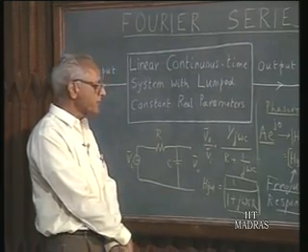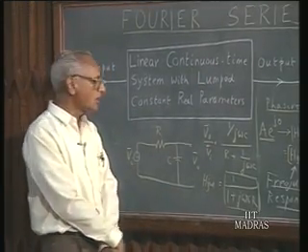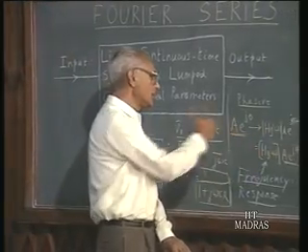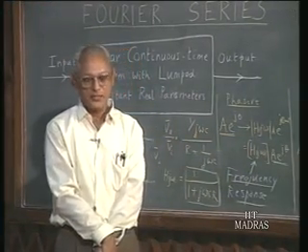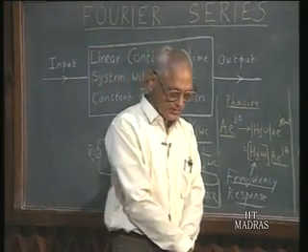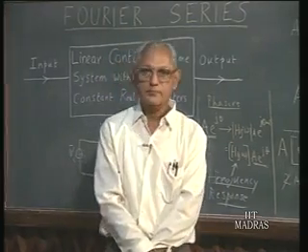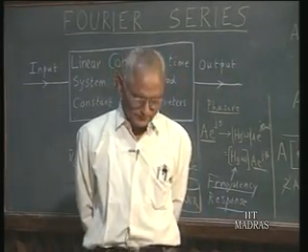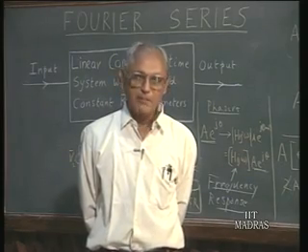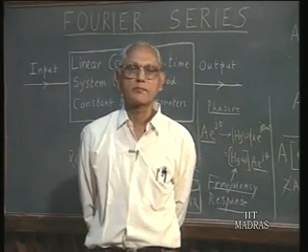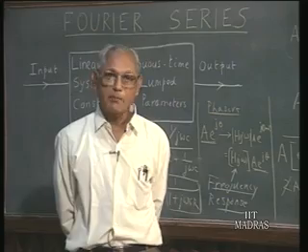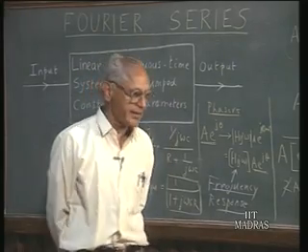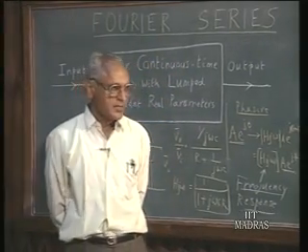And what is meant by frequency response function? It is the ratio of the output phasor to the input phasor under steady state sinusoidal conditions. However, in practice, in real systems, we may not always have excitation functions which are sinusoidal. They may be periodic and non-sinusoidal. They may not be periodic as well. They may be aperiodic.